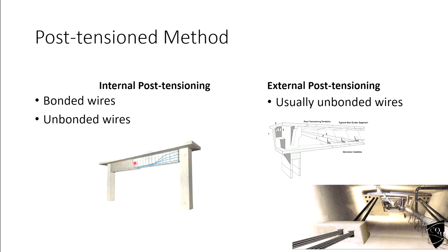But in internal post tensioning, you need to have the section, but still the section height will be much smaller compared to RC beams because of less deflection.